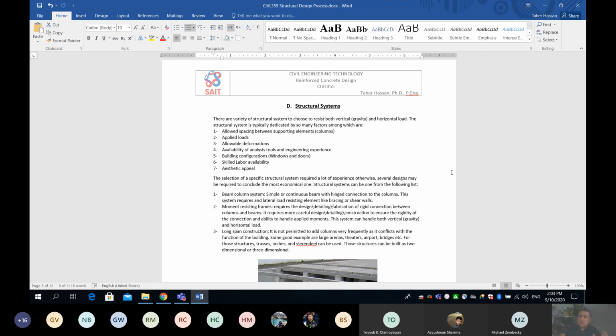Can anybody tell me, anybody who was in this arena or close to it and looked at the roof, what is the structural system? What do we call it? I know that you guys know this name. Any help? Open web steel joists or rafters. Oh, thank you so much. So here we go, OWSJ, which is open web steel joist. And to be honest, in industry we don't call it an OWSJ. I know that they have the same name, but we call it truss.